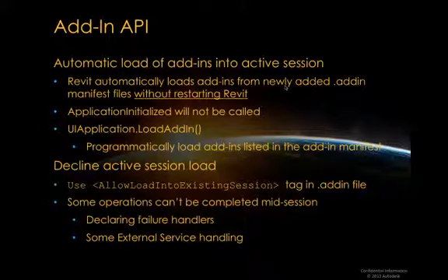An add-in can decline to load into the active session. That is done by setting a specific tag in the add-in manifest. And obviously some operations cannot be completed in this situation. So, as said, an add-in that participates in this needs to deal with it. The reason why this is important, obviously, is to enable add-ins to be downloaded by users from the Autodesk Exchange store and tested immediately without the need to restart Revit first.